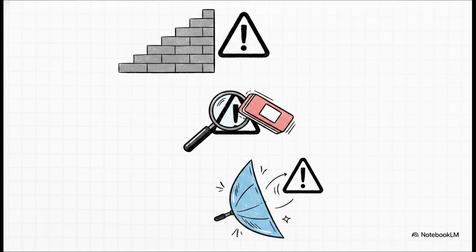First, hazard avoidance. This means designing the system so the hazard is physically or logically impossible. For example, building a two-handed operation switch on a heavy mechanical press so the operator cannot physically have their hand under the blade when it drops.